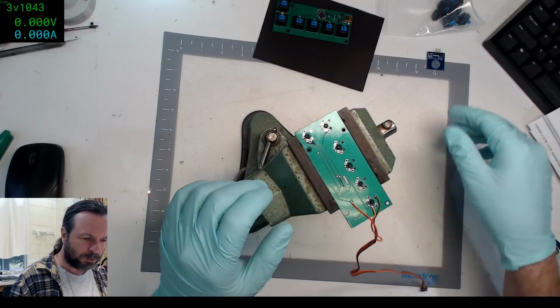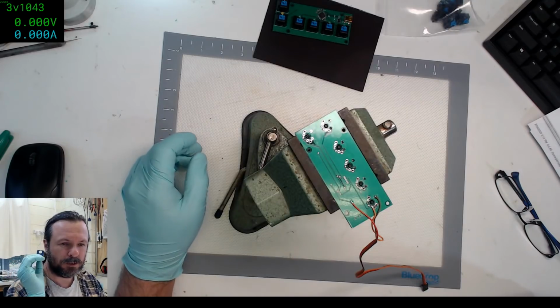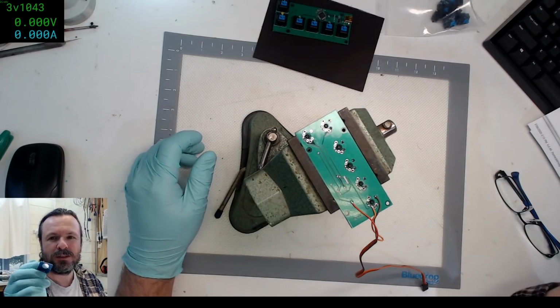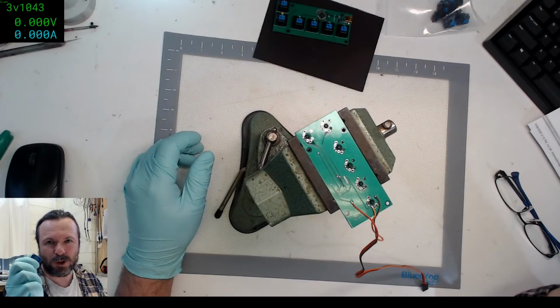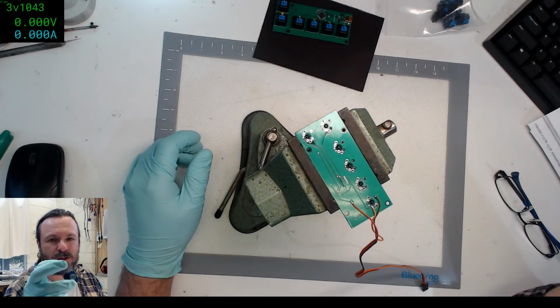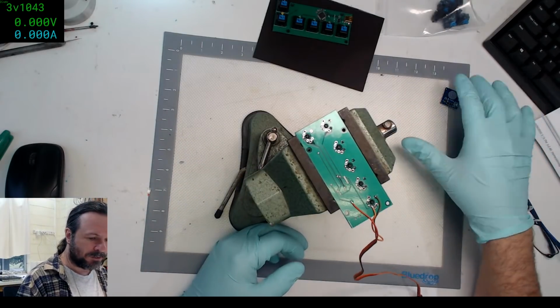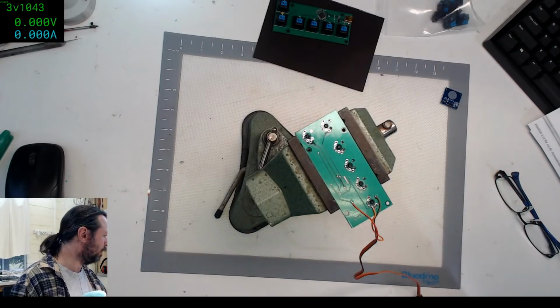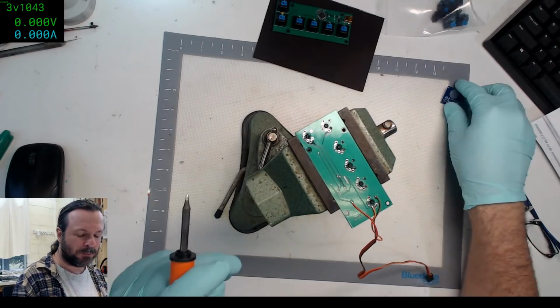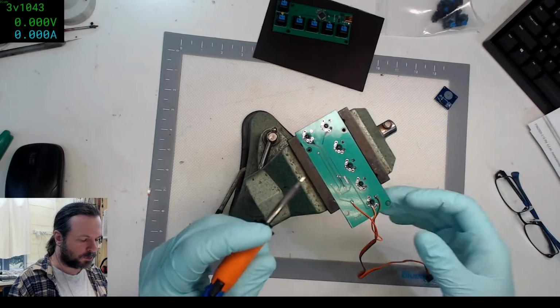No, that's not the problem. The problem is that when you have an active pull-up, your line is effectively high the whole time, whereas this actively drives the line when it's been pressed. So it's a conflict of the signaling styles. The capacitive thing can pull down that 10K no problem, but the trouble is, because it wants to drive the line, it causes a conflict.